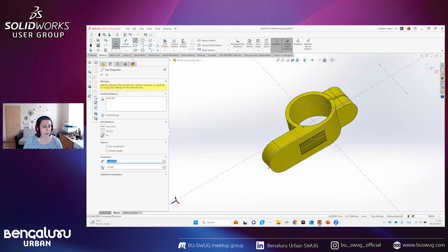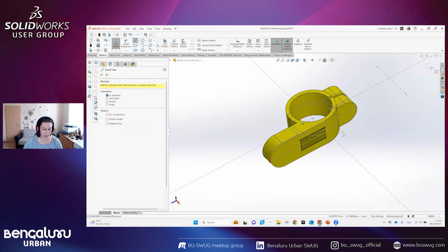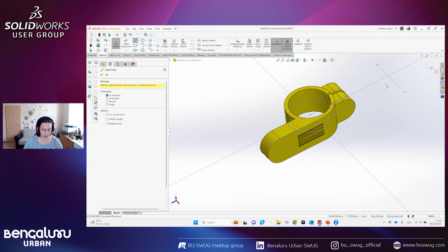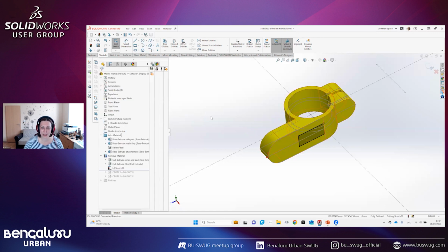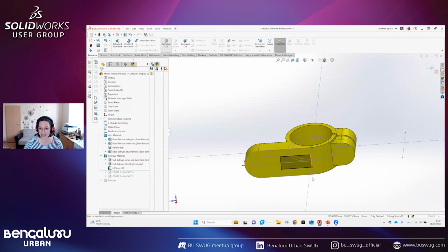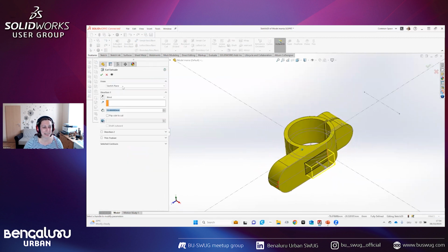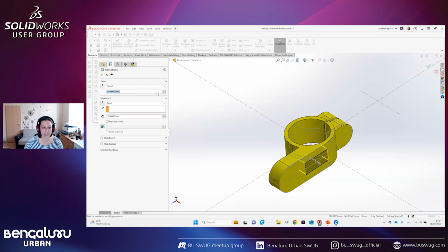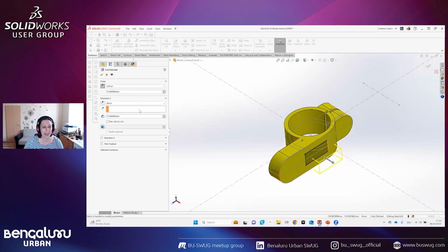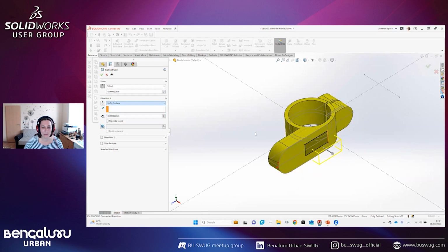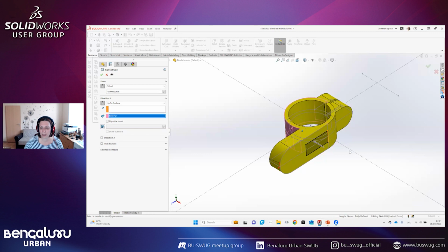And then I will cut to this face, but very often you will receive a funny result if you start directly from a tangent face. So the trick here and the workaround is, when you start the extruded cut, you're not starting from the sketch plane, but give some offset. And then you say up to surface and choose not this one, the inner one.